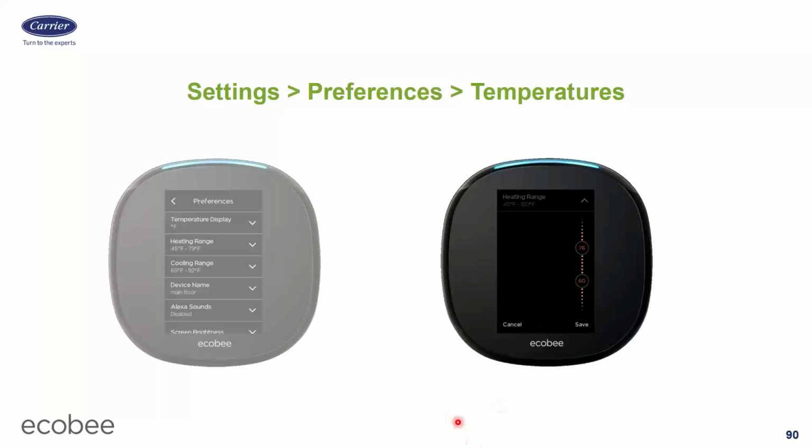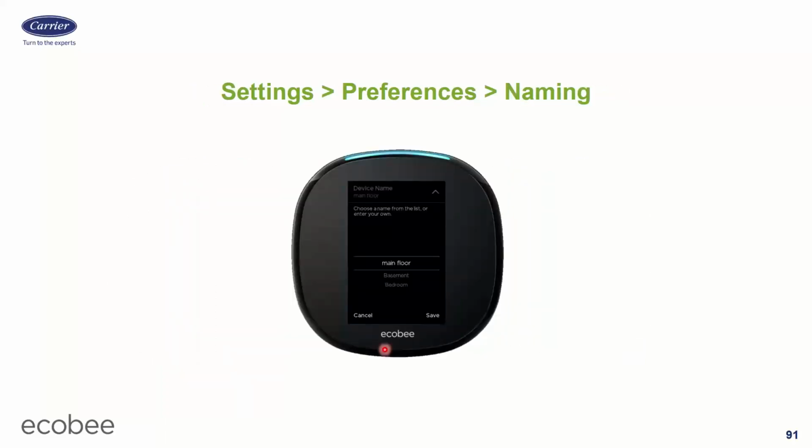Or we have a lot of these Ecobee stats at our own buildings at TEC, and I think I have the heating locked between 61 and 73. 12 degrees is the closest that you can make it. So that's how I somehow ended up at 61 and 73. So none of my coworkers can lower it below 61, and nobody can jack it up above 73 for heating. But they have control within that range. And the same thing for cooling, obviously. It works the same way. So you can do that. You can tighten it up a little bit if you want to.